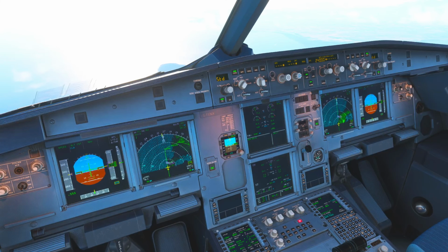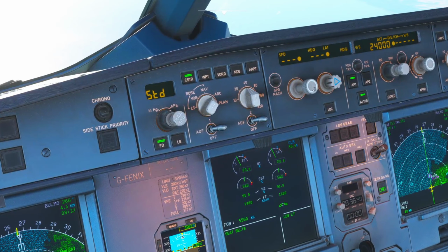So here's the trick: push and pull knobs and buttons. Knobs can be pushed in or pulled out, giving control to the flight management system in managed mode by pushing it, or setting manual control, the selected mode, by pulling the knob toward the pilot.